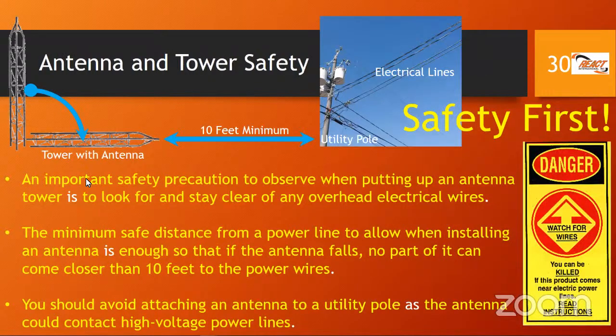That's the first bullet point. An important safety precaution to observe when putting up an antenna tower is to look for and stay clear of any overhead electrical wires. Very important, folks.